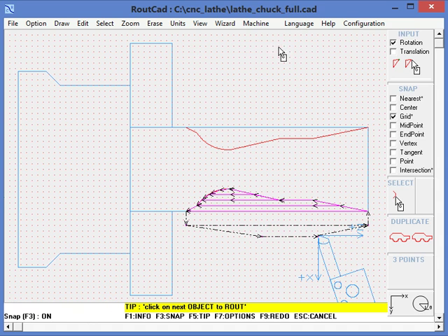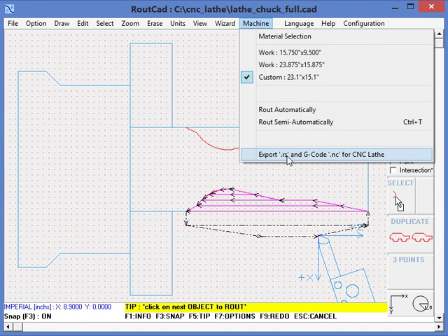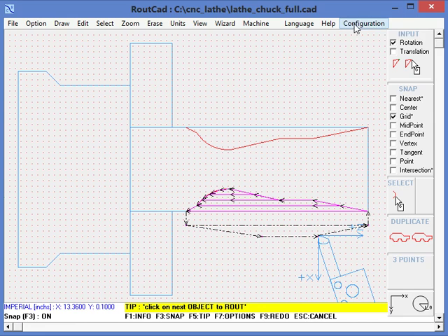If we go ahead and export this G-code, obviously we're going to make sure that the configuration is correct. If everything is okay and we export this G-code, it will do a complete closed path, in the sense that the CNC will machine the surface of revolution and at the end go back to the exact same location it started from, which is good.